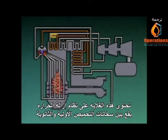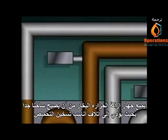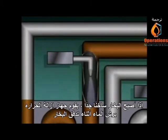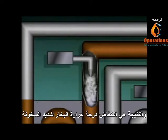This boiler has an attemperator, or desuperheater, located between the primary and secondary superheaters. The desuperheater keeps the steam from becoming so hot that it damages the superheater tubes. If the steam gets too hot, the desuperheater sprays water into the steam flow. This water immediately flashes to steam and mixes with the steam that's already there. The result is a decrease in the temperature of the superheated steam.